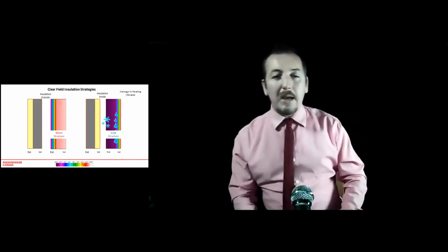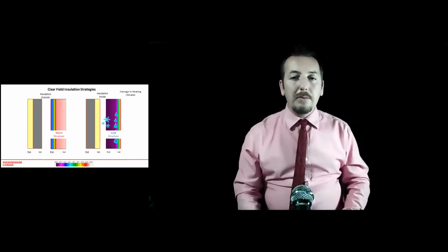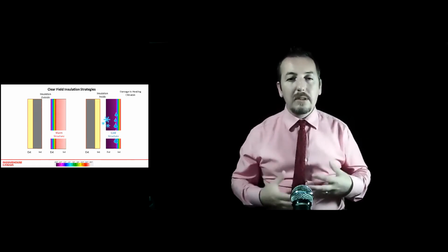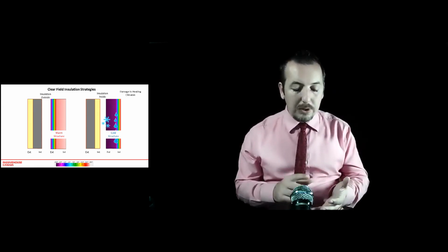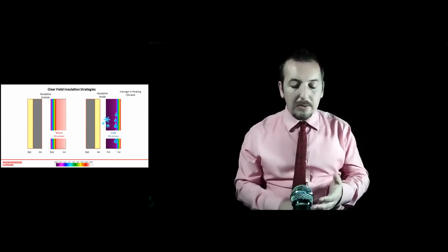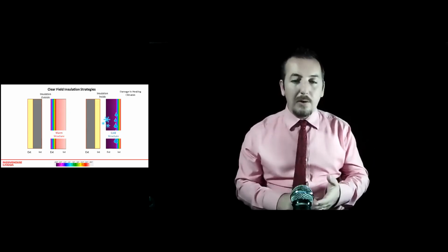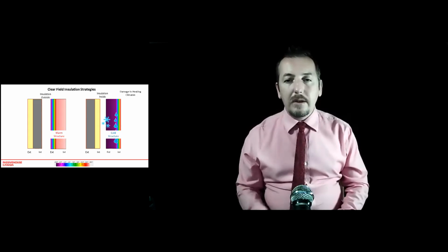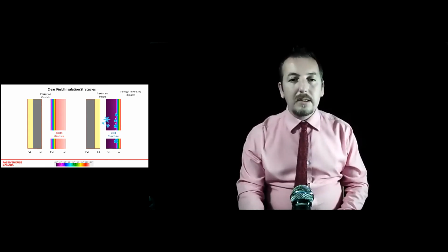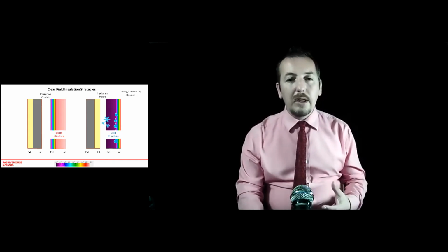Now, there are exceptions, but they have to be dealt with in almost every case with a hygrothermal simulation, where you can track the moisture movement in the wall, because there are so many factors. Hygrothermal takes into account climate, the amount of moisture materials absorb, rainwater. There are so many things involved that it has to be taught as a science in itself. But generally, if you're externally insulating, you're on the safe side.